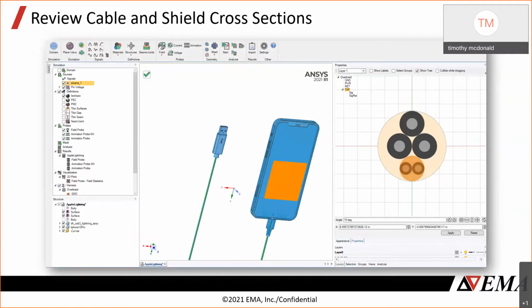And so in EMA3D cable, we've got the ability to have multiple shield levels, branches and cables. This cable doesn't branch, but if it did, we could resolve that. We can handle foil braids, foil shields, braided shields. We can twist in the cable shields. And specifying those cables takes seconds. There's a pre-built library of standard types, or you can specify manually, but it really is as simple as just right-clicking and adding conductors or importing an export from the standard wire diagram software tools.